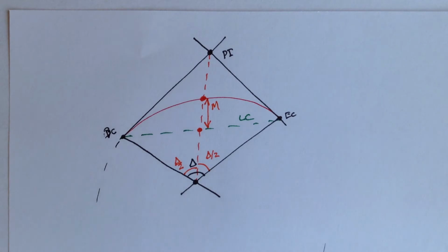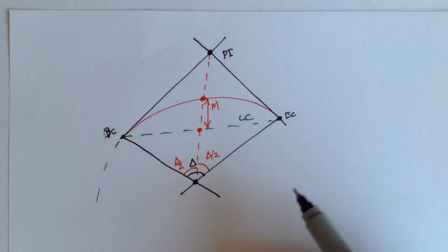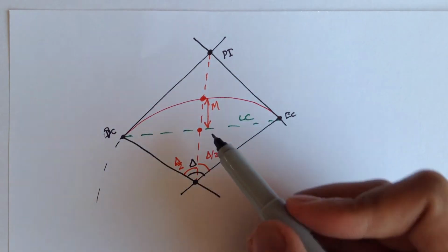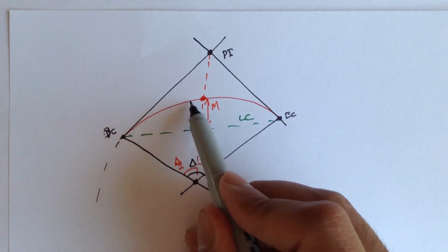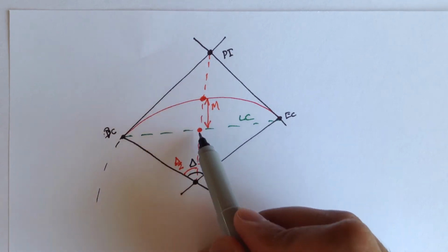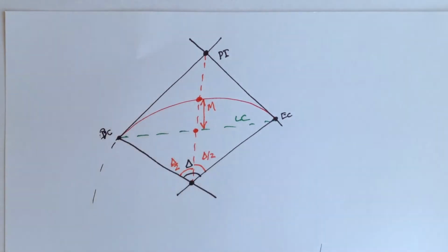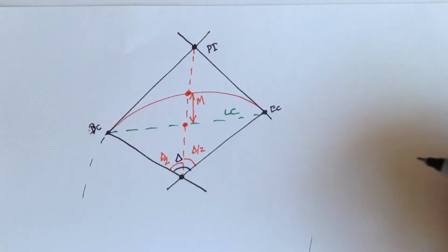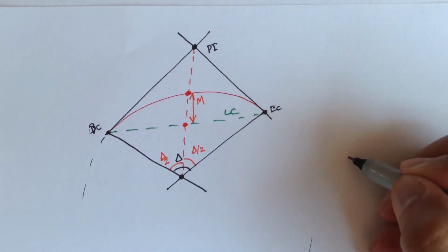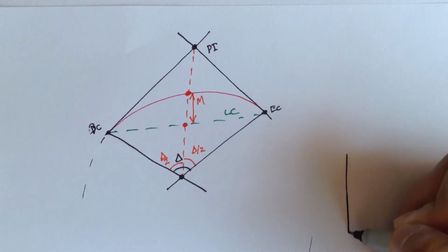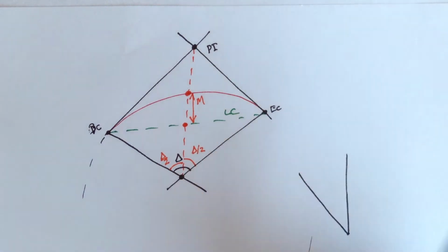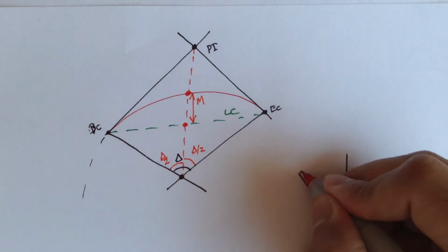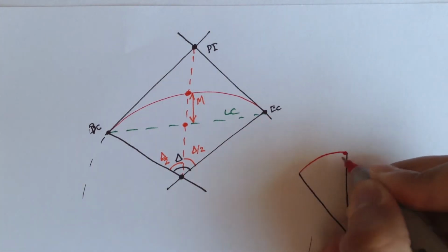And how do we figure out what the middle ordinate is? Well, we can use geometry. Let me redraw this segment here. From the BC along the curve up to this point, then down to the origin, then back to the BC. I'll draw the curve in red.